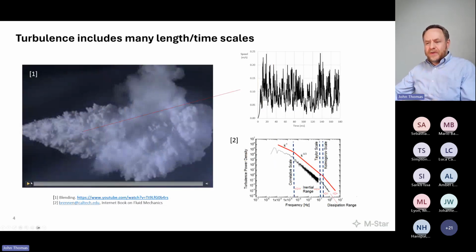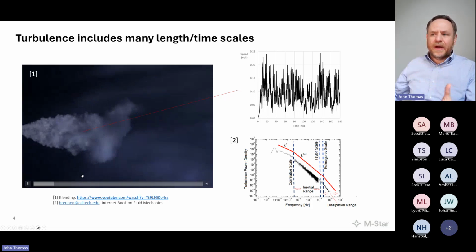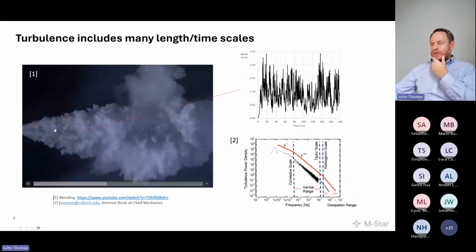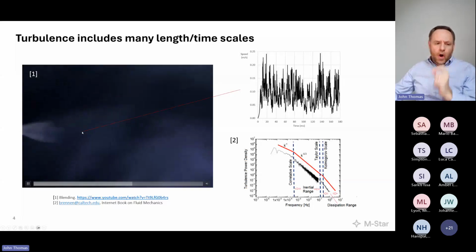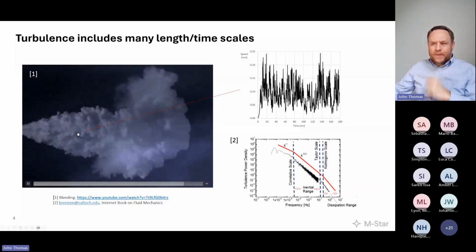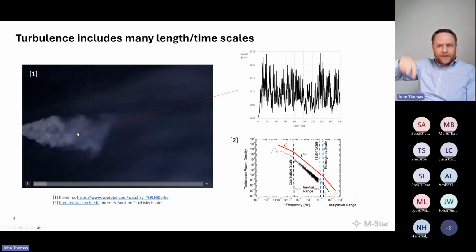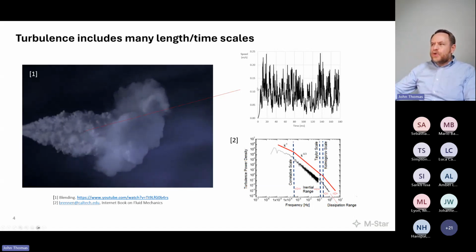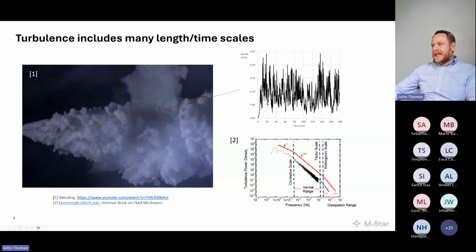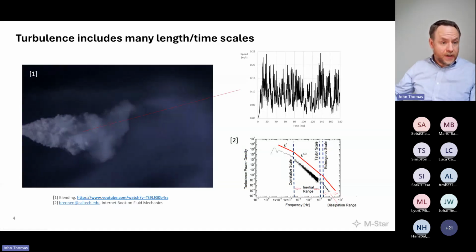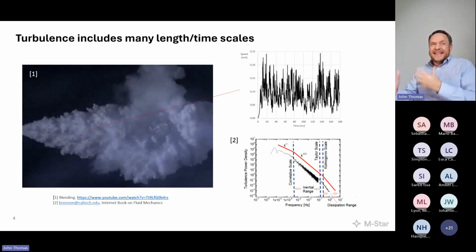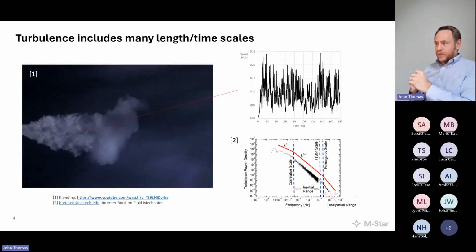And these principles are general. So here's a jet mixing, or rather I should say a nozzle. We don't have a jet mixing system. Here's just a nozzle. There's no classical recirculation. If we squint real hard at this or our previously demonstrated systems, and we look at one little point, we'll see there are periodic velocity fluctuations, and we can do things with this signal. We can take a velocity autocorrelation function if we wanted to, and an integral of that gives us some sort of a time scale associated with turbulence.